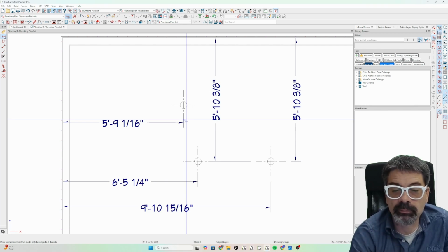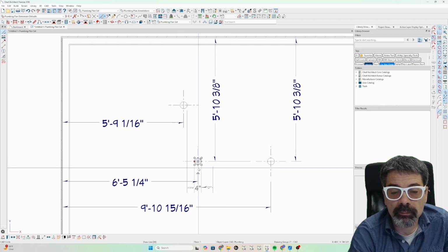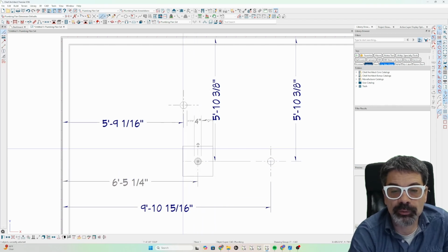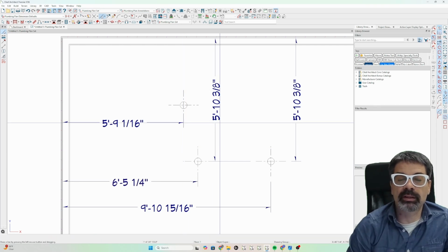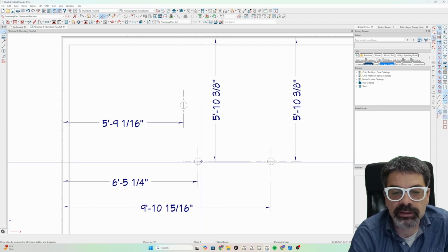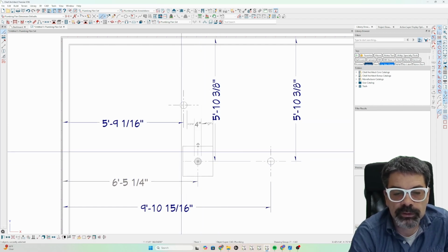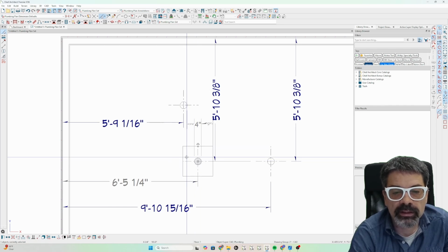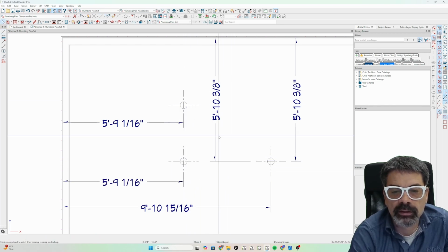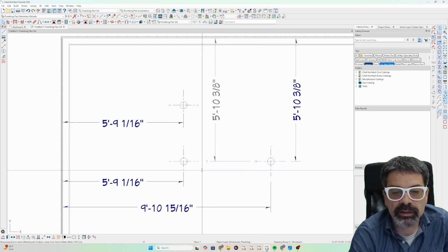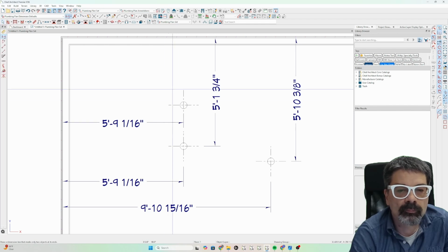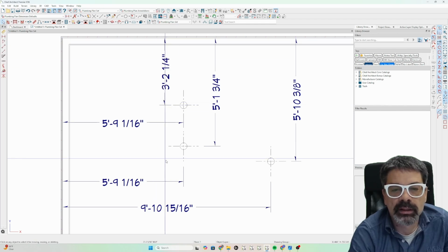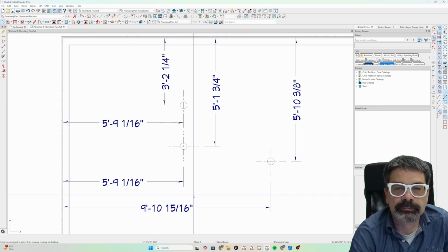Now, let's go back up to this example on the top. If I'm moving this circle, I need to select all 3. I'm not moving, use point to point. This example down here taught me something. The point-to-point dimension will create a point in the first location that you click, and it will actually connect to the center of the circle in the second location. So it does not connect to this circle, but it does connect to the second circle where I let up on the dimension.